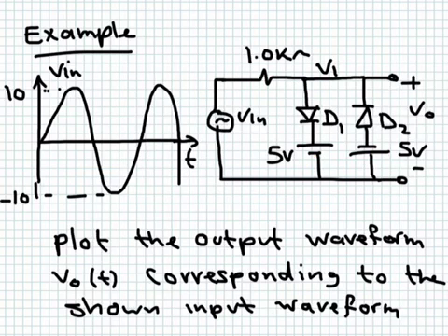So there isn't 5.7 here. Okay, so you are still waiting for your input. You start to apply your input signal. You make it 2 volts. If you make it, say, 2 volts, is this sufficient to turn this one on? No, because you need 5.7.